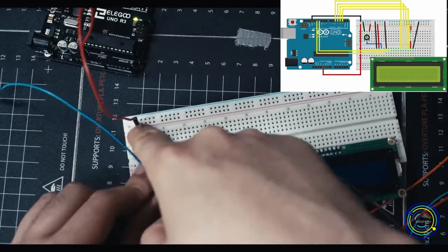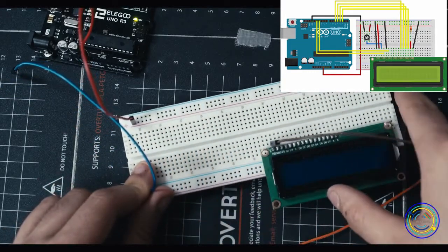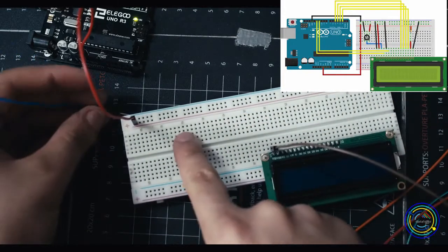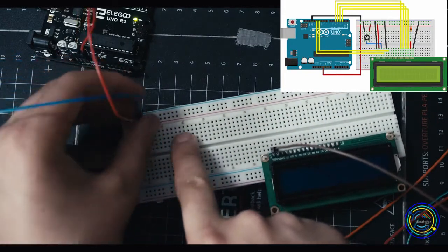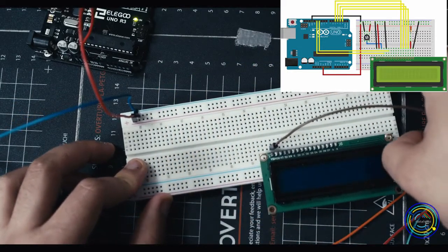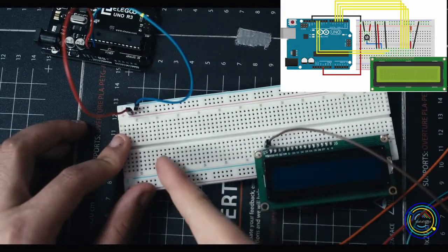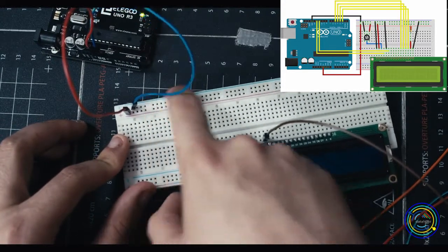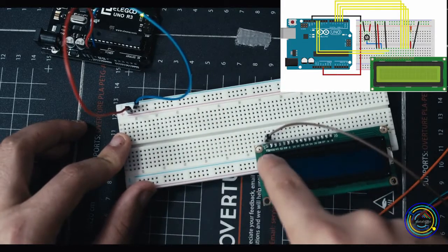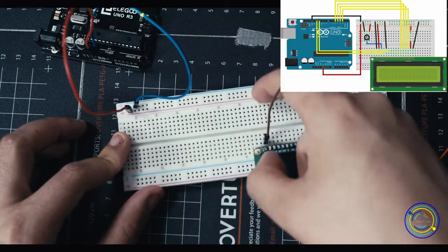Now that we plugged in here on this red line, this whole second row on top is all going to be power ports. Then if we plug the ground into the one right on top of that, that whole first row is going to be ground. One thing you should know is when working on a breadboard, these lines right here are vertical, these are horizontal. So when I plug something into VSS here, it's not activating the horizontal line, it's activating the vertical line.